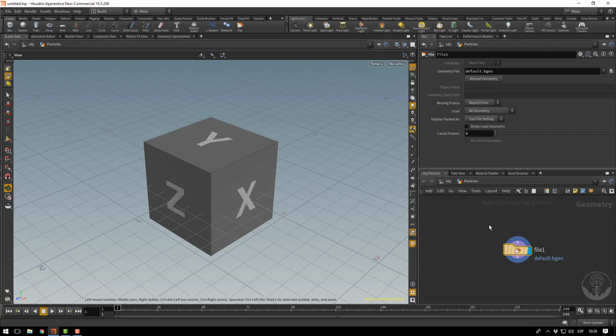This means that the SOP is a surface operator and includes all the modifications and attributes that you add to an object. That means adding normals, colors, deformations, whatever change we've been doing till here happens in the SOP level.